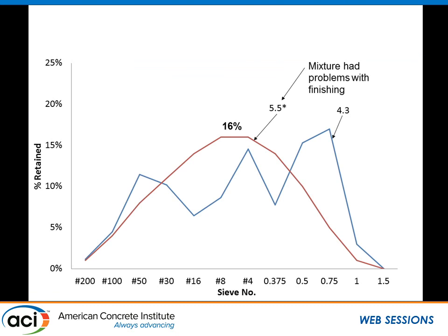And I'm actually really proud of this plot. I love it, in fact. We actually sieved it to get the perfect bell-shaped curve, which in every single concrete textbook is suggested as the ideal grading. It's the perfect Power 45 curve fit. And we saw it didn't have some magical performance. It performed just a little bit worse than an aggregate we can get down the street. Okay. This is important, though.